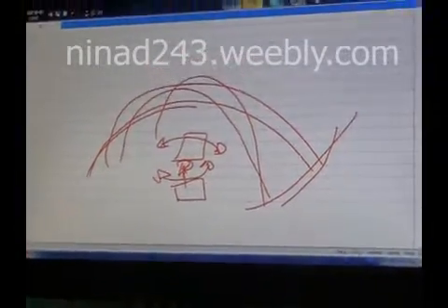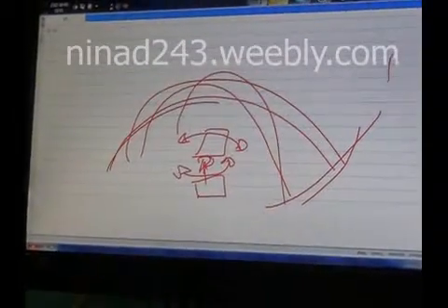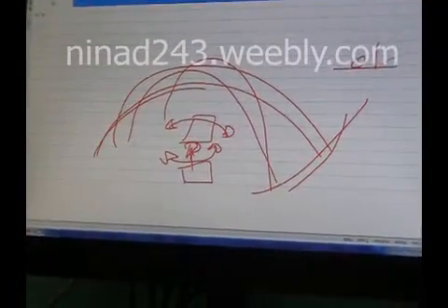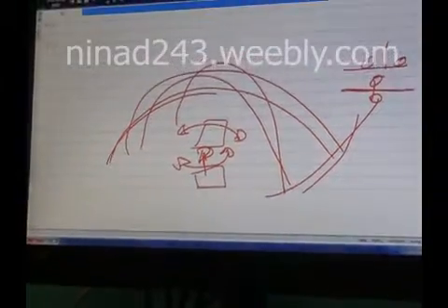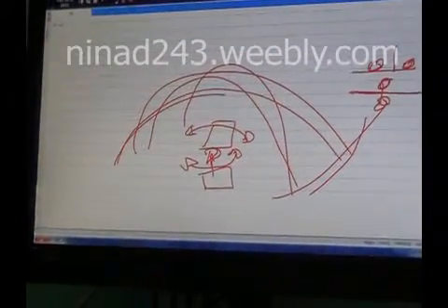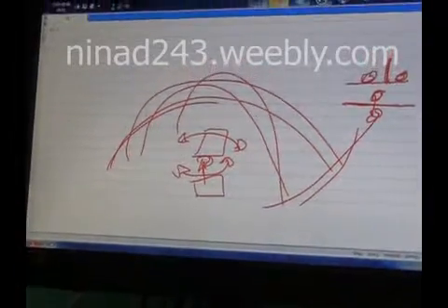And again the same mechanism is used for feedback. One LDR will be facing perpendicular to the sun always, and the other LDR pair will be something like this. One on this side, one on this side. So this is the plate, two LDRs. This is the plate, two LDRs. Okay. So this is how the two axis sun tracking system works.